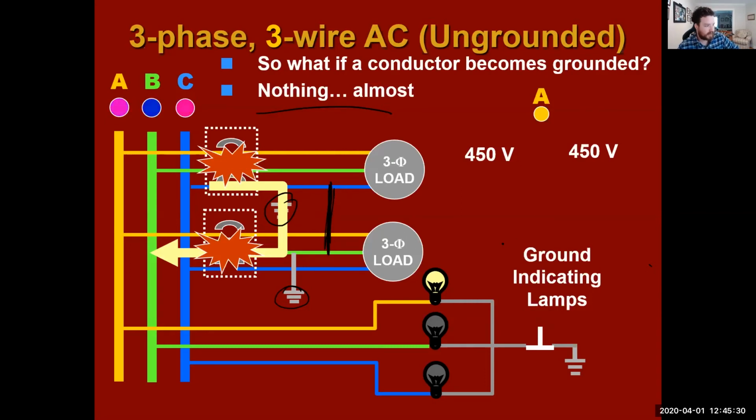And it's not like this is a lead-lag scenario with air compressors. You don't choose when you have grounds. This isn't a normal operating condition. So you have to go chase these. You have to make sure that you have taken care of all of your grounds, so that in case you get another one, which you will,